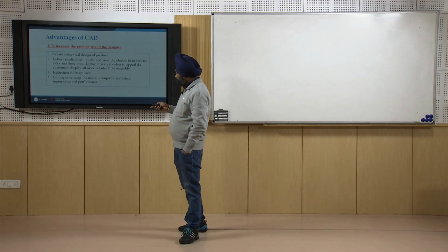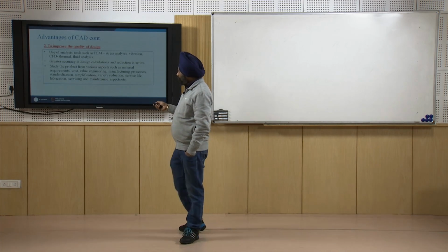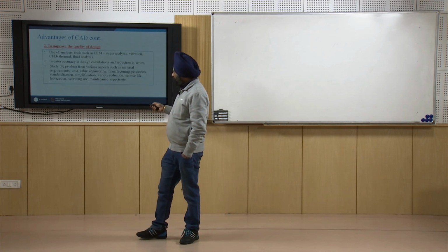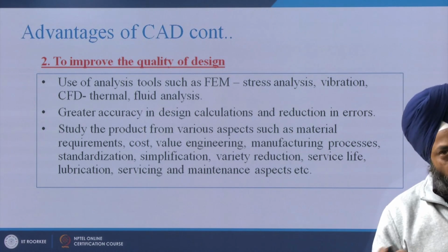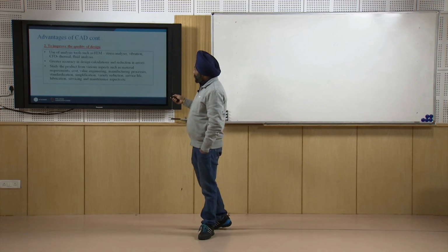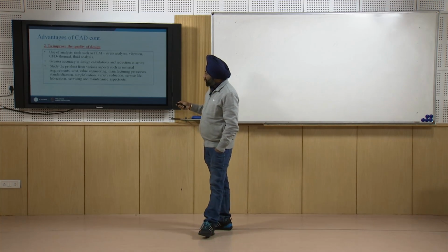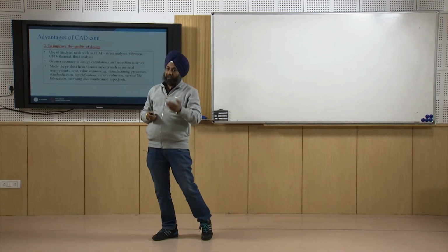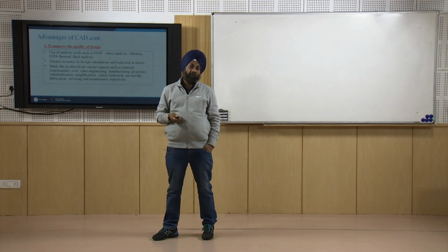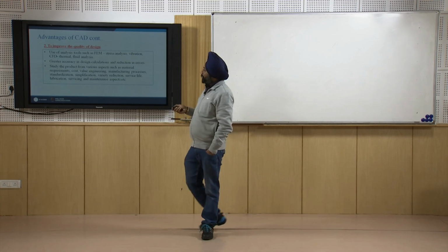So it improves our productivity, it improves the quality of designs, it can use analysis tools such as FEM analysis tools. As I have already discussed, you can do FE analysis based on the CAD model, stress analysis, vibration analysis, computational fluid dynamics, thermal analysis, fluid analysis can be done very easily. So we can integrate our CAD model with the analysis software and do a complete analysis of the product.